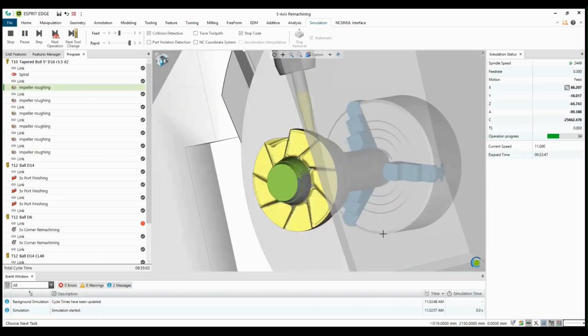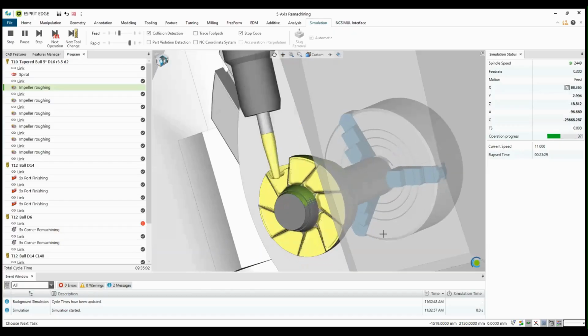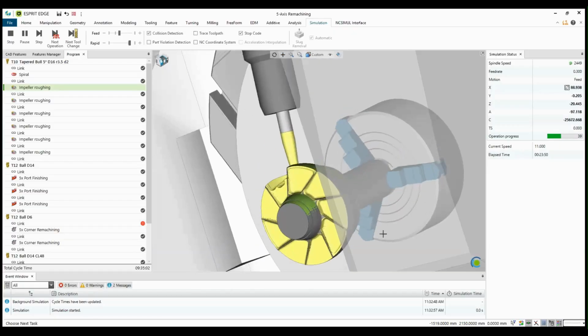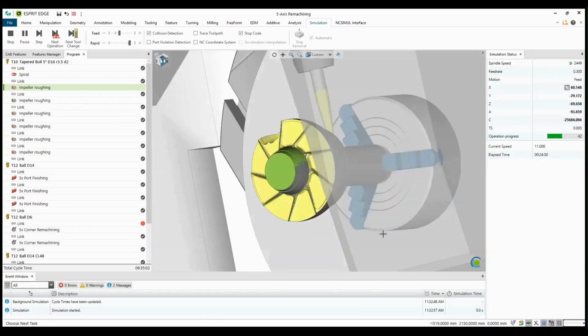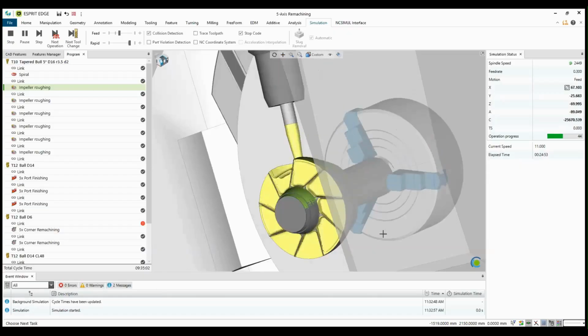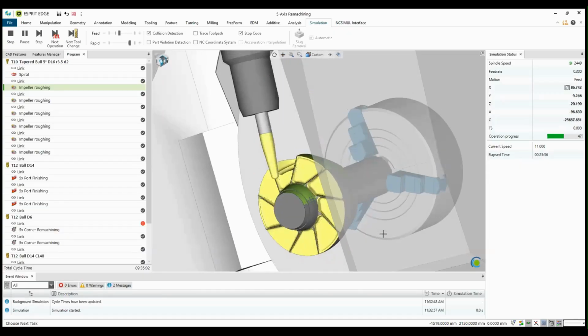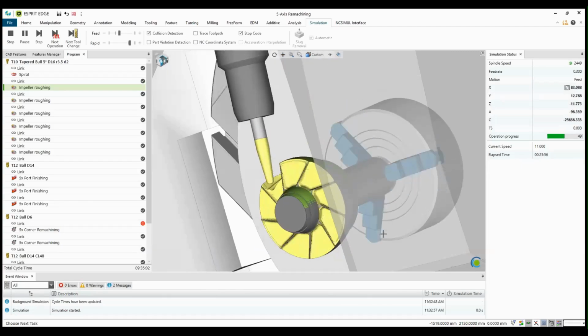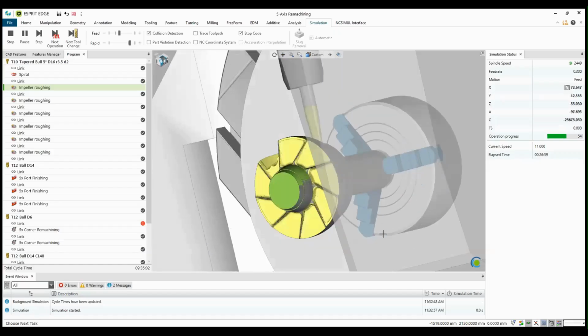If you use a different tool here than on the real CNC machine, it will not be the same comparison. So whatever holders, tools or inserts you are going to use on the real CNC machine, you can create the same in ESPRIT Edge as well. And you will also see the toolpath simulation, so that we will not get any surprises on the real CNC machine.